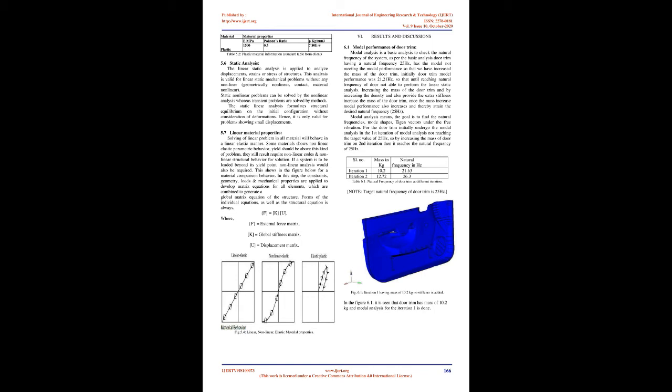6. Modal analysis of the front doors reveals that they are on target. Modal analysis results are obtained for 10 different modes. Of these, the first 5 modes are local modes and the remaining are global modes. The modal frequencies obtained are greater than 20 Hz, which is well away from the engine excitation of 16 Hz. This result is for an ideal condition of the engine.